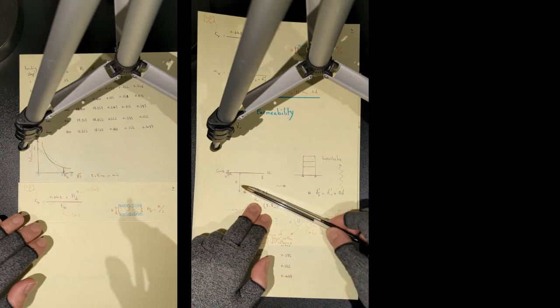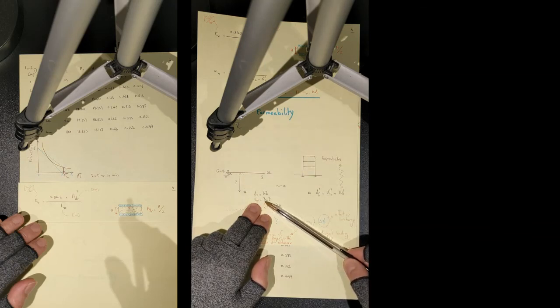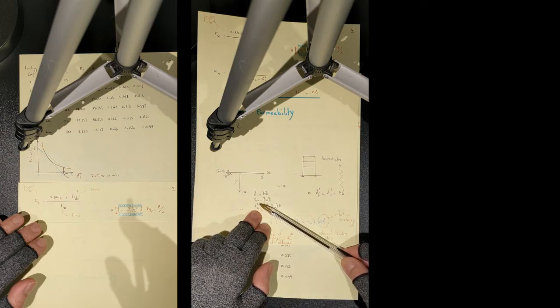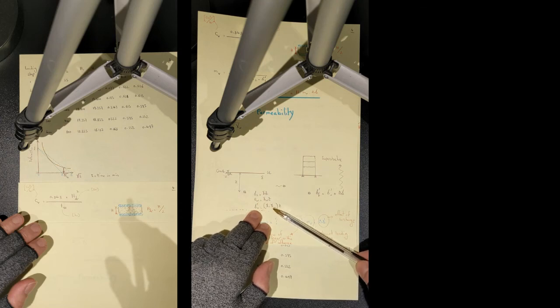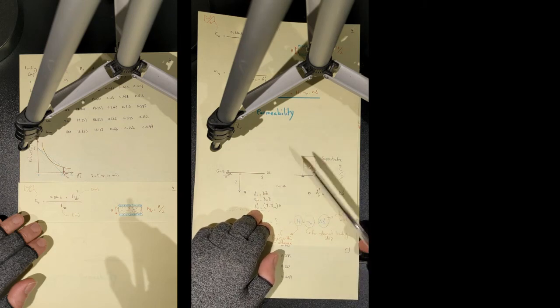This is the height of column of water standing on your point of interest. So your UW is gamma W Z. And you can use the principle of effective stress and calculate your initial effective stress. That's sigma dash naught. That is equal to gamma minus gamma W multiplied by Z, or sigma minus UW. Okay, this is your initial effective stress.